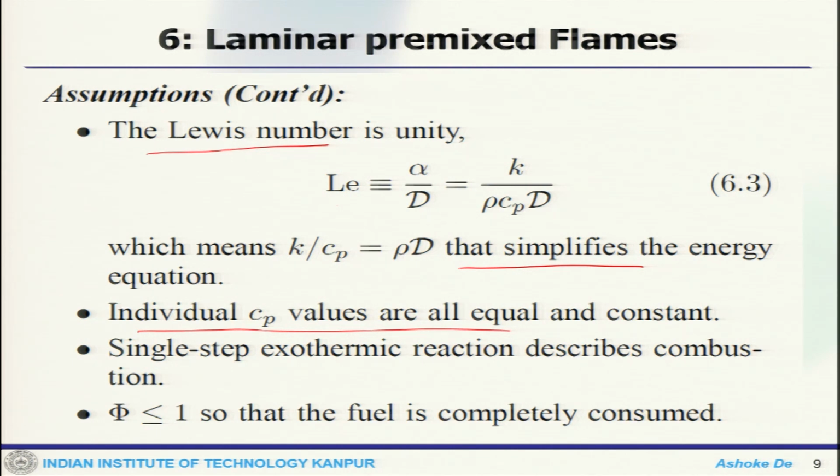Then kinetics, which is important, because when we are talking about the reaction we have to take the kinetics into consideration. So, this is a single step, that means it is already simplified, essentially a global kinetics exothermic reaction, and we take a lean condition, that means the fuel is completely consumed, which is not a rich condition.